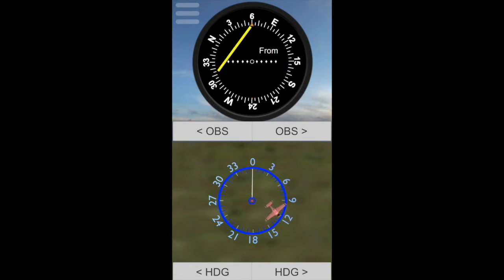So if I'm anywhere here, it's a from. Look at the aircraft. The aircraft is anywhere on this side, that half circle, that slice between the 330 and 150, getting a from. Watch what happens when I jump to the other side. It's a to indication. Again, heading doesn't mean anything. Your heading of your aircraft doesn't matter at all here.